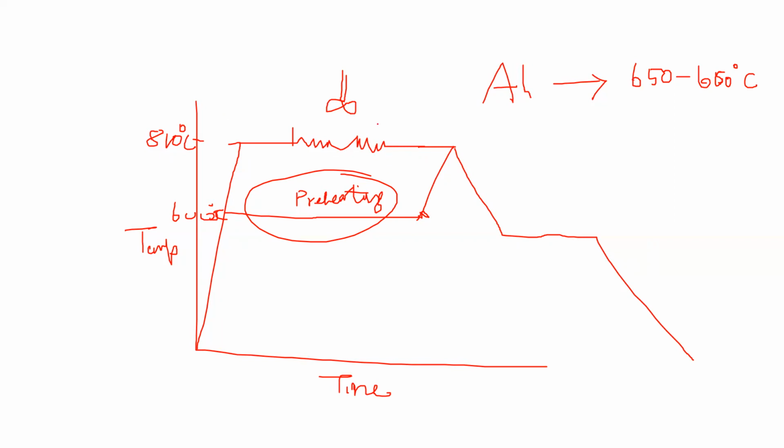So while doing this stirring action, the reinforcement particles are introduced into the crucible. After the introduction, the stirring is continued. The stirring may be done at 300 RPM for 30 minutes or 40 minutes. It is based on the type of material and how much reinforcement particles you are adding. So it depends on these parameters.